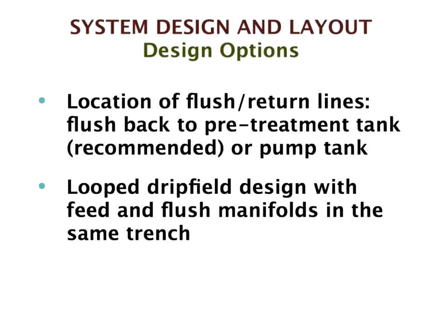Okay. You have to locate your flush and return lines. We recommend that you flush back to the pre-treatment tank. Sometimes we'll flush back to the pump tank. And there are also circumstances on very steep slopes when one might flush down into a tank and then have another pump pumping it back up to the treatment plant. Loop drain field designs are quite popular because that reduces the number of trenches, and you can have the feed and flush manifolds in the same trench.